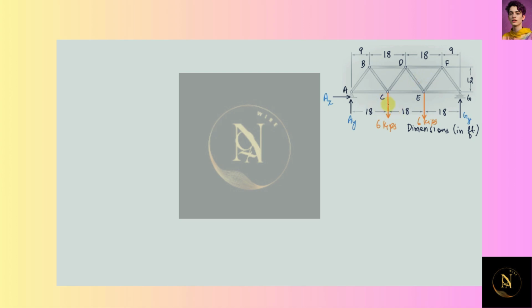So here in this problem we are given this truss and we have to calculate the force in each member, and we have to also state whether the member is in tension or compression. To solve this problem we'll first be calculating the reactions, that is AX, AY and GY. For that we'll be using equilibrium conditions.